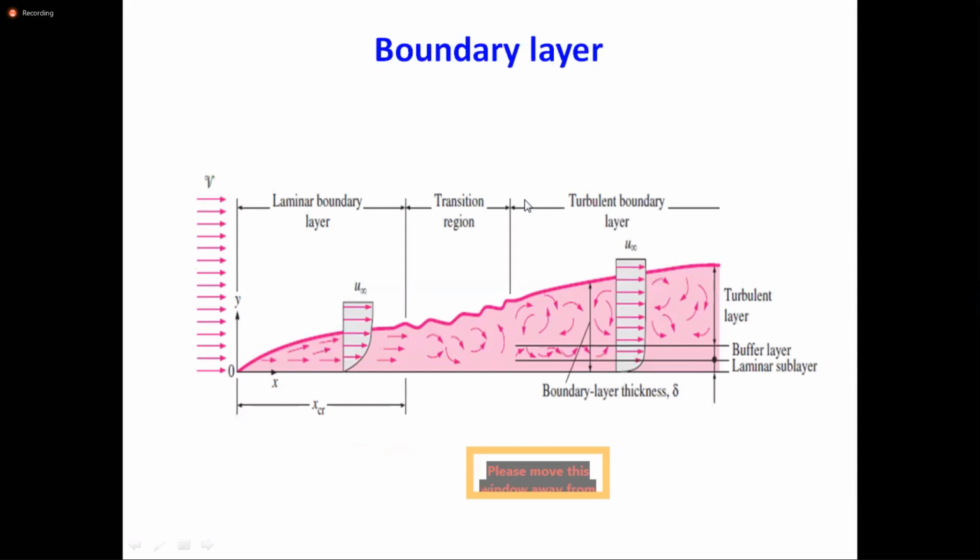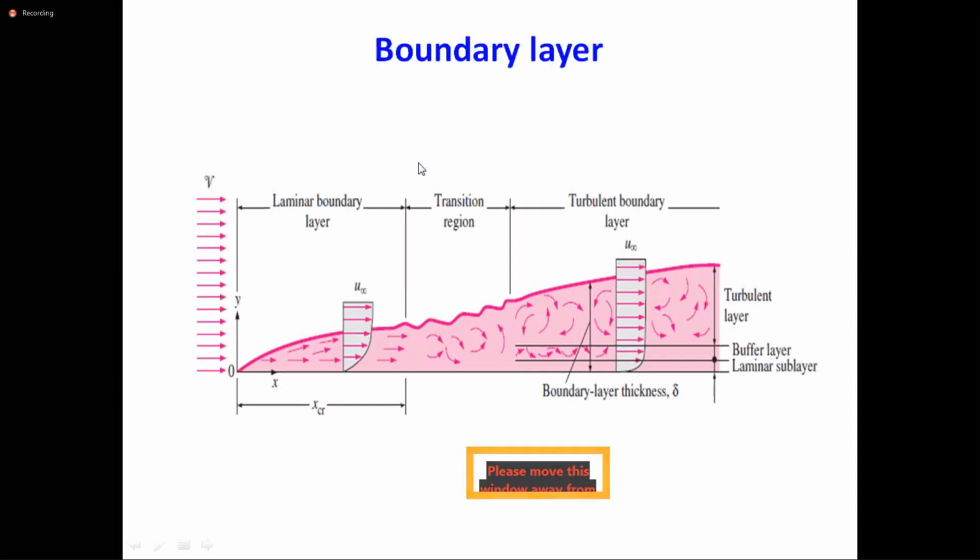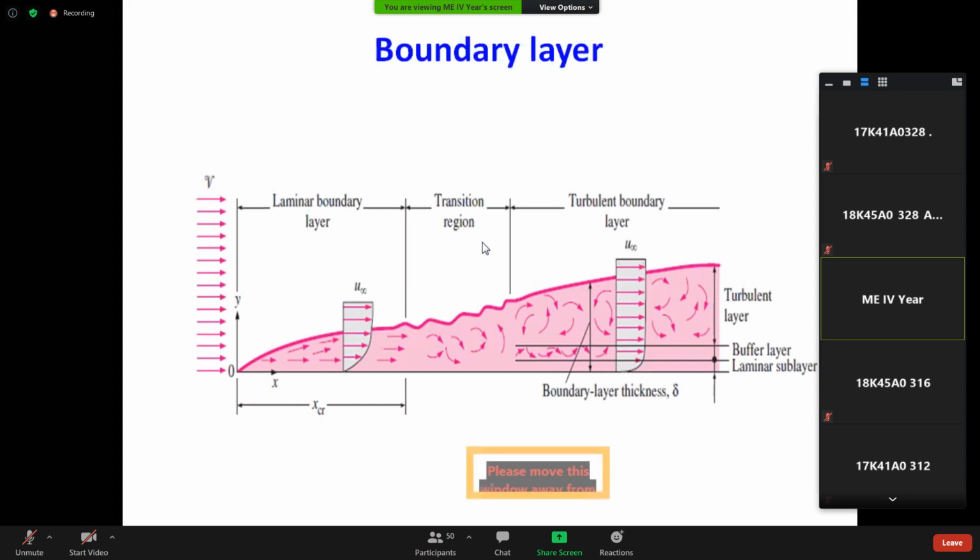Before giving the heat transfer convection problem, whether it is a flat plate or internal flow, don't bother about natural convection. I'll discuss the condition also. Whether it is internal flow or external flow, the Reynolds number is essential. I'm talking about the external flat plate now. So here you're supposed to calculate the Reynolds number, and based on it, we move forward for the further solution.